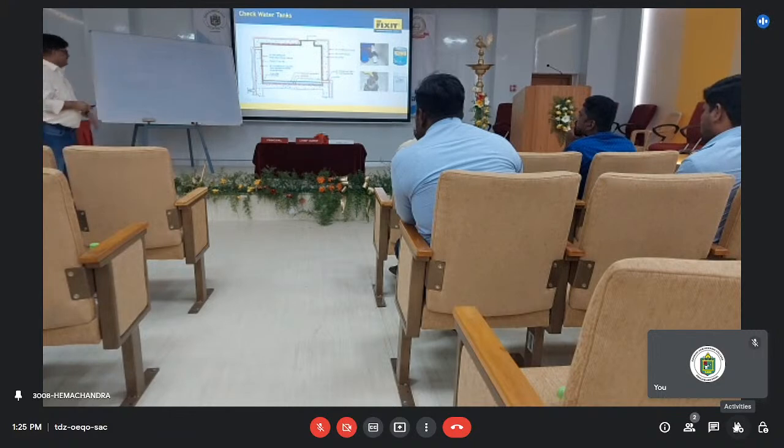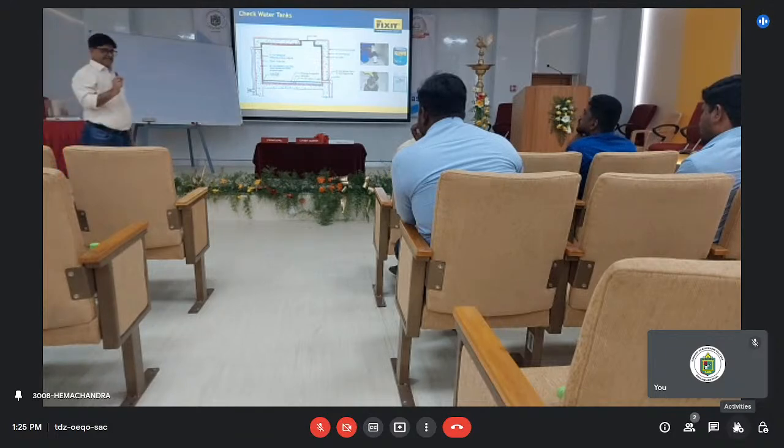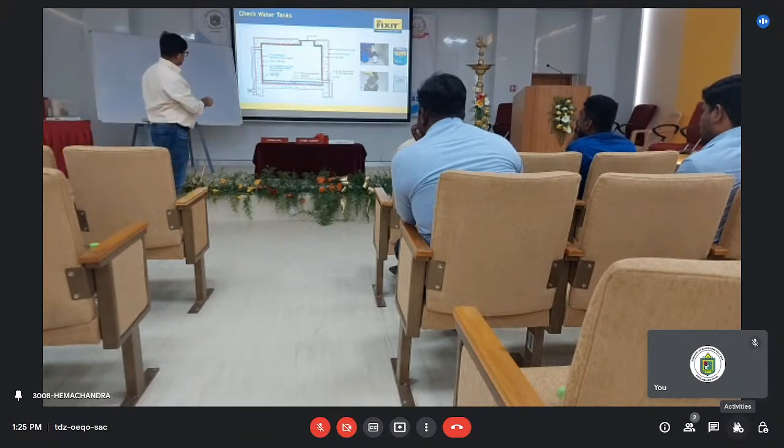Finally, with the water tanks, this Ashwati has again taken care of, but make sure that grouting is done properly at the joint points and all the corner areas, and then you can do the coatings and others. Whenever you have a water tank, it should be coated on the top. Sometimes people miss this section to be coated. Okay, they only do the vertical and the below. They skip the area above the head, they don't do the coating. But the areas above the head are required to be coated.